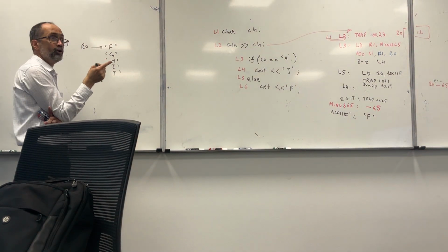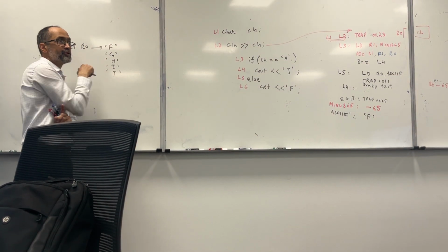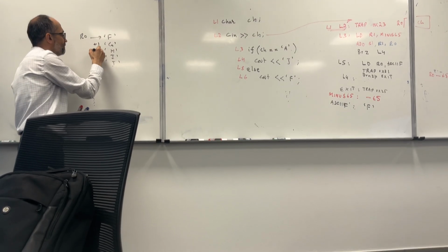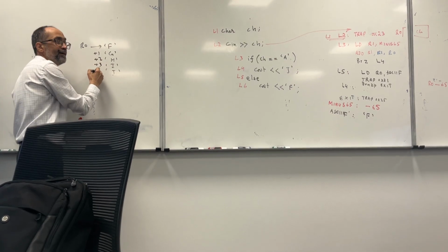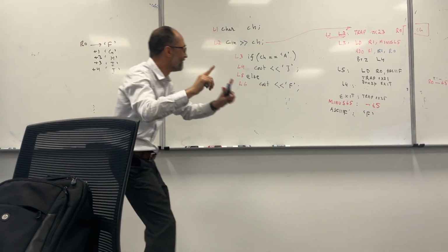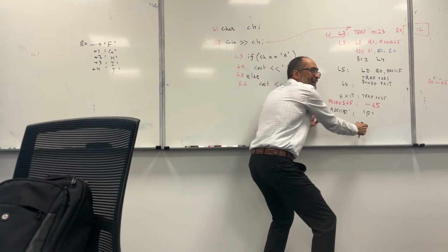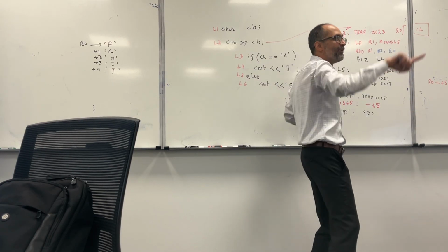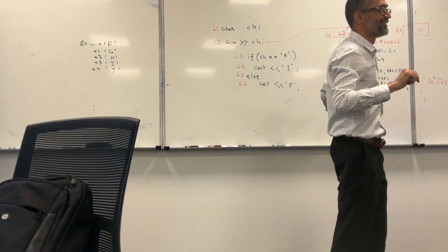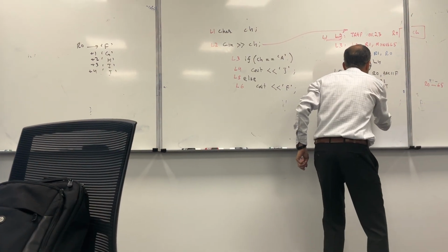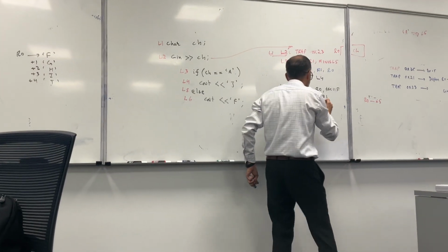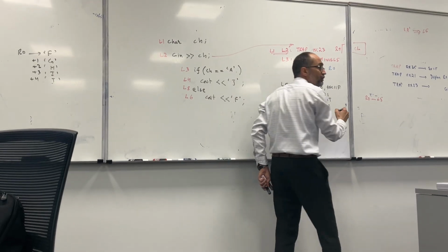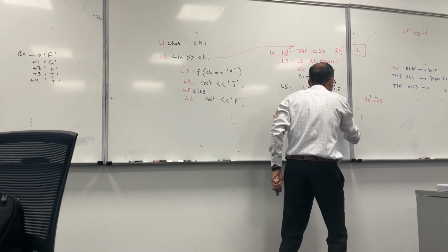Now we want to store J. What is the difference? Plus 1, plus 2, plus 3, plus 4. So please remember, I can also have the ASCII value of J here, but I have to do the load. Instead of doing that, I want to minimize the number of instructions. Add R0, R0, hash 4.